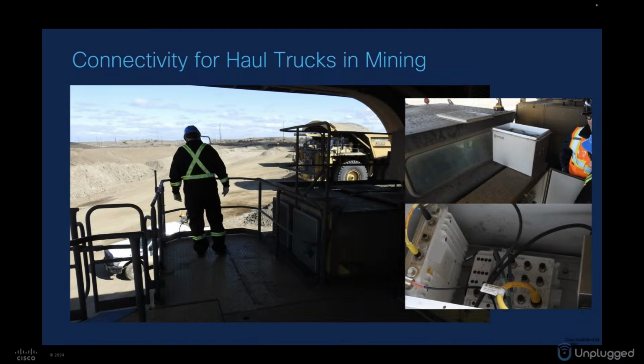There's a Workgroup Bridge in there that is connected to a hardened IP67 Ethernet switch that is providing connectivity on multiple VLANs to the systems on board for tire pressure monitoring, for axle weight monitoring, for engine control monitoring, all the attendant systems that often have to be in their own broadcast domains.